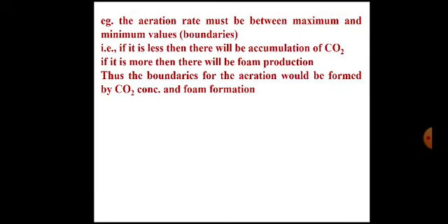Likewise, the aeration rate must be between maximum and minimum values. That is, if it is too less, then there will be accumulation of CO2 and the cells will die and it will decrease the productivity. If it is more, then there will be foam production.